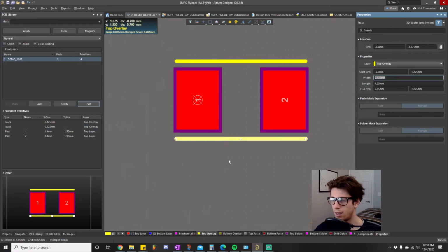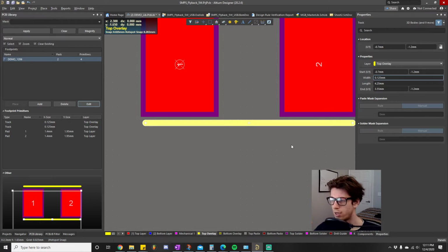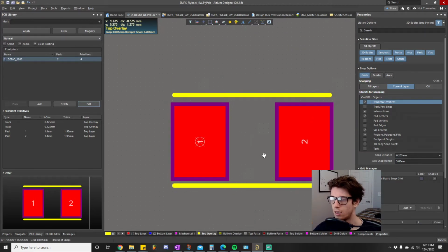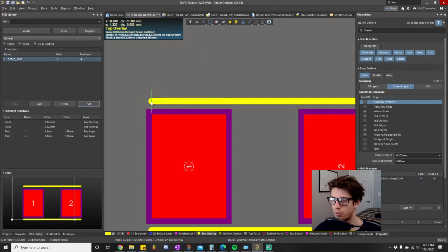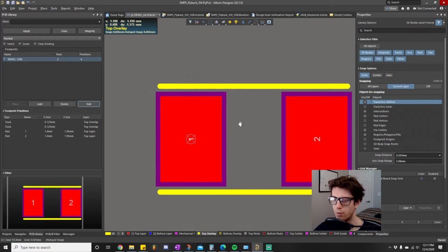Right? And now we can actually bring it in a little bit closer. And we will have to check, I think, because there's a design rule that talks about silk to solder mask clearance, and depending on whether you can change it, whether it's within the footprint or not, but what I want to avoid is increasing manufacturing costs because the silk to solder mask clearance is too low.